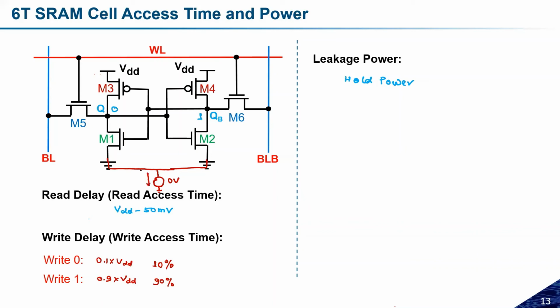Directly you cannot calculate the current through the wire. In the simulation tool, you can just calculate the current through the transistor or some of the devices. That is why you need to connect one 0 volt voltage source between this node and the ground, and then you can calculate whatever current is flowing through this voltage source, because the voltage is 0, so the potential difference is 0. Whatever current it shows will be the same as the concept we made before.